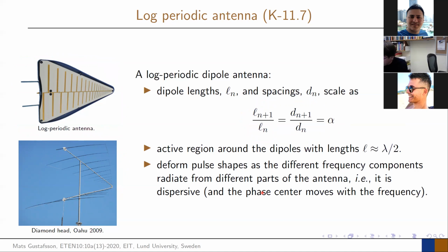And in principle, you can think about it as different dipoles that are resonant. It's an antenna that does not really have the radiation pattern of a pure dipole. If only one of these were resonant, it would really be a pure dipole pattern like a donut, but it's not. It's a pattern that is more similar to that of a Yagi-Uda antenna with three elements. So it actually has a directivity in some ways. It does radiate in one direction.